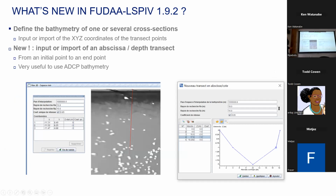Last, something we also added in the last version was the possibility to use what we call the abscissa depth transect. It's very useful when you have ADCP bathymetry. ADCP will give you a distance and a depth. Using this option in Fudaa-LSPIV, you can just click on the beginning and ending point of the ADCP transect and import the distance made good and depth data from the ADCP.